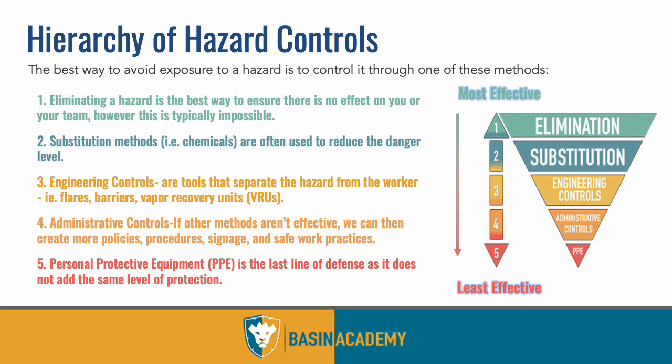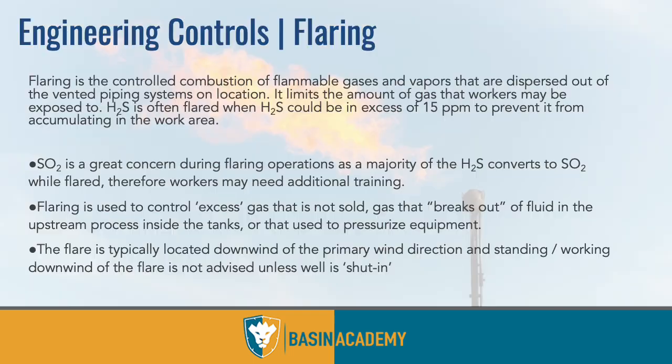For us, we've found that through chemical treatment, through different safe work practices, where you stand, how you stand, where you direct the flow, do we vent, flare, different pressurized systems, different tools you can use, subsurface, there are different ways to protect yourself. So that's where I lean and the industry leans, and those are the best ways to protect yourself. PPE being the least effective method of protecting yourself.